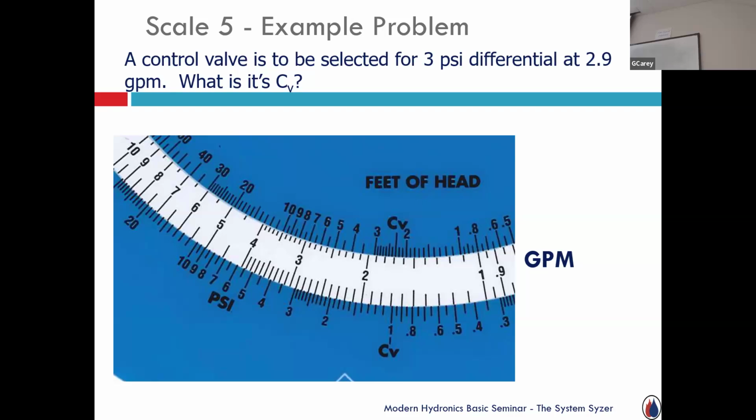So when that downstream capillary or whatever's measuring says, hey, I'm starting to get warm, and that valve goes to close, there's an impact, a much more accurate decrease of output. So you don't overshoot, because otherwise the valve shuts right down because it overheated. Then the discharge temperature or the water temperature drops and you open it back up. Then it overheats again, and it's doing that, hunting.